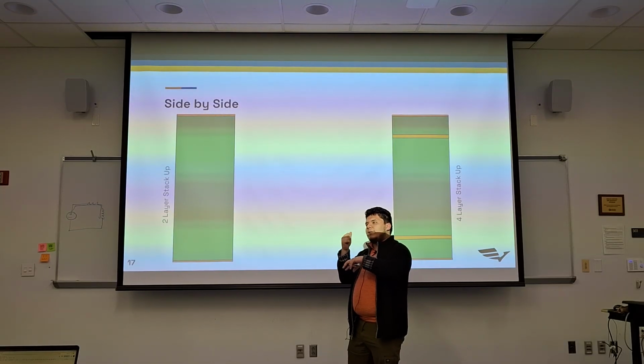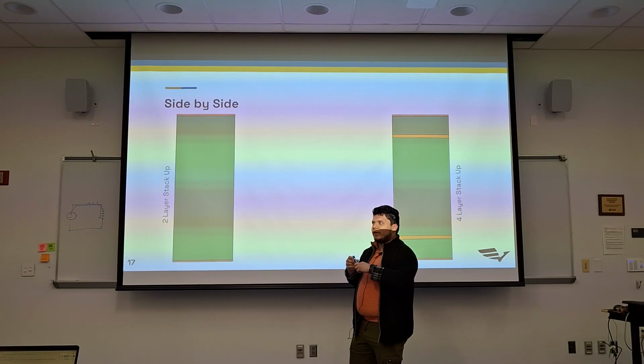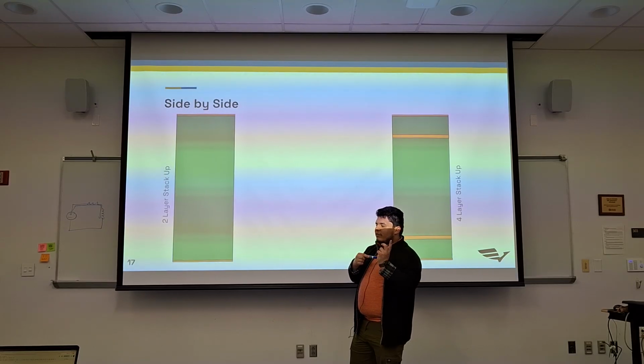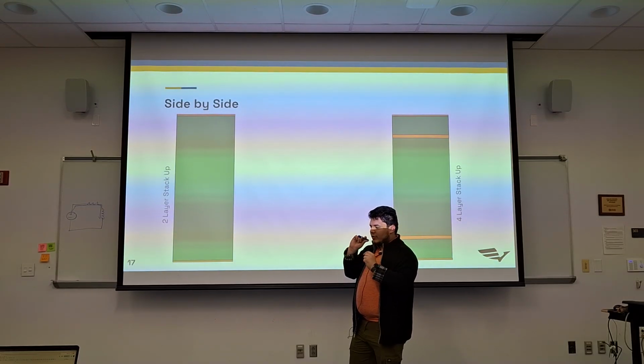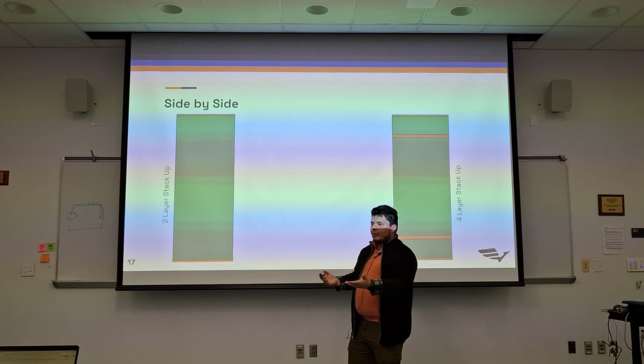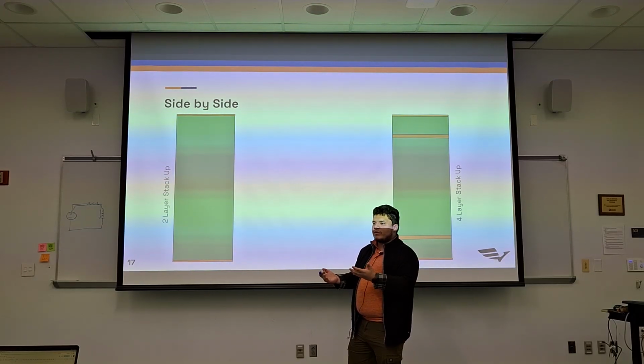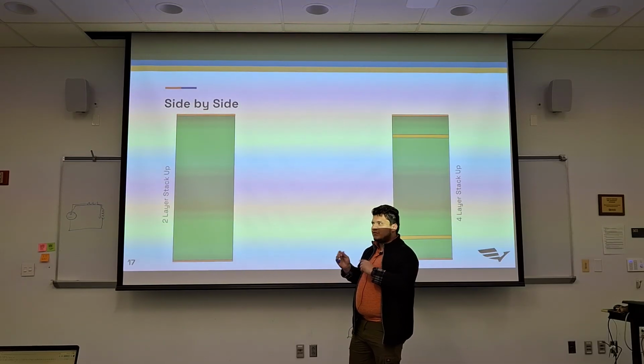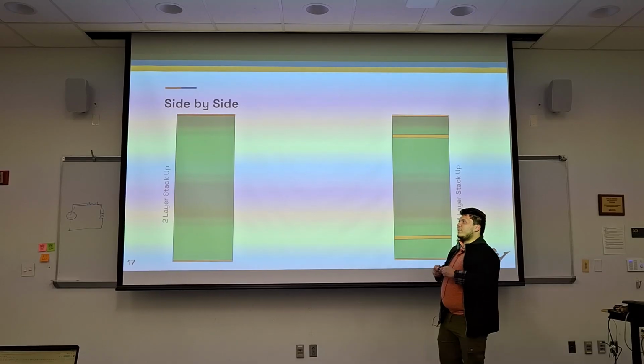And this is something that I go into as one of the pitfalls, because I noticed that a lot of the designs that I looked at were starting in the top layer and then viaing into an internal layer, but you could have just started from the internal layer, because your through hole is like a massive via, right? So if you have a bunch of through hole connectors, you can always utilize the fact that they're through hole, you know? So we can go into that when we get to the vias.